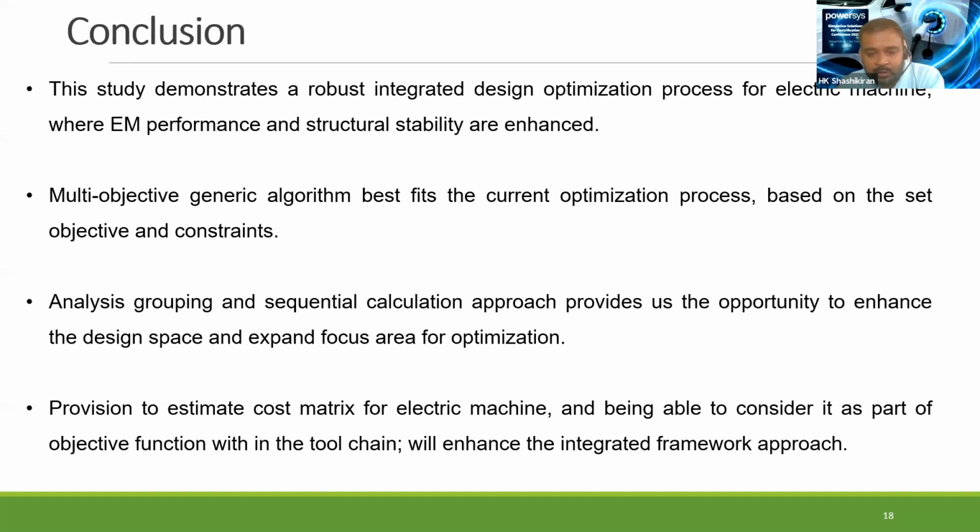But on the losses, of course, we need to have correction factors because JMAG doesn't include the mechanical losses or the churning losses. So that needs to be added externally to get the efficiency number. Efficiency numbers are not directly correlated with what we have from the tool. So we need to have an external correlation matrix included if you really want to get the correct efficiency number.